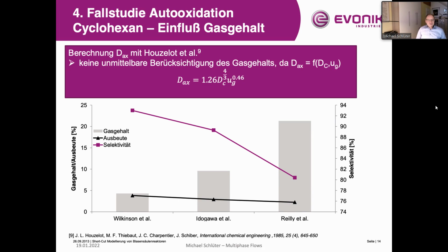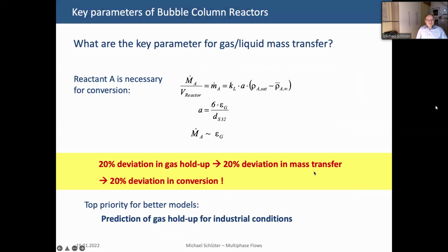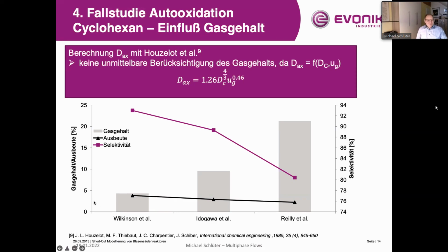So in other words, your reactor can be 4 times smaller if you use the correlation from Rayleigh than by using the calculation of Wilkinson. And of course, as a good engineer, now you will probably say, I will be on the safe side of life and will use the Wilkinson correlation, and let's build the reactor 4 times higher, and then I'm safe.